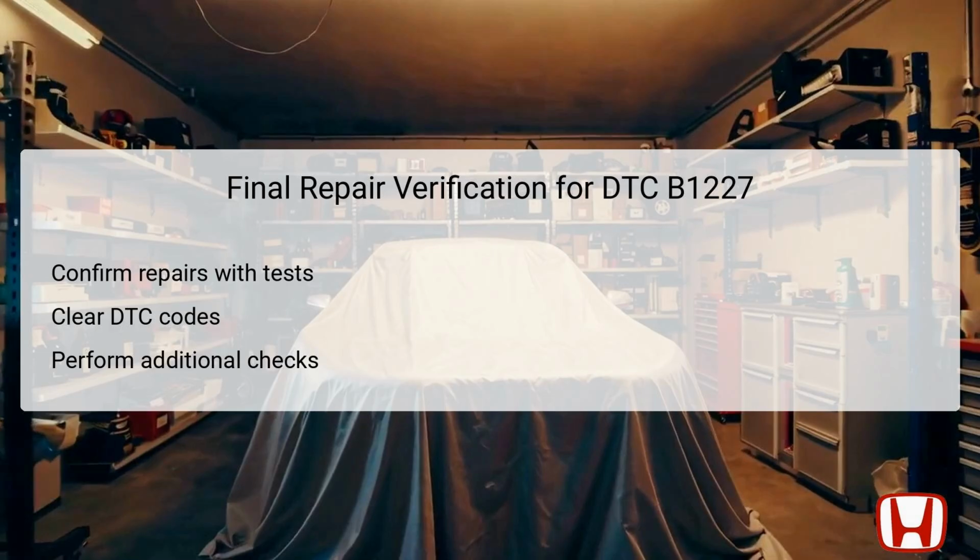Once verification tests are satisfactory, clear the DTC codes from the vehicle's memory. Performing additional checks is also wise to ensure that all systems are functioning correctly and that no new codes have appeared.